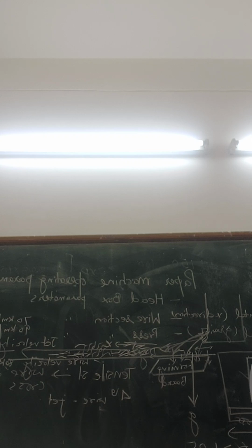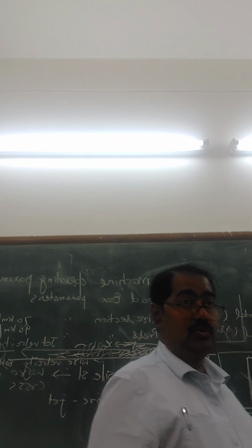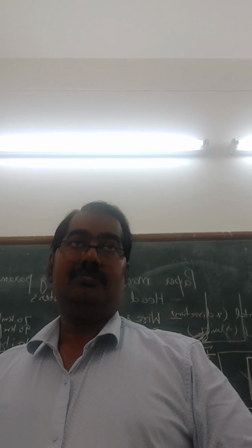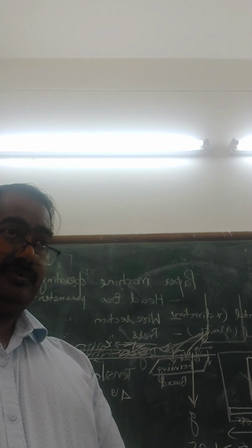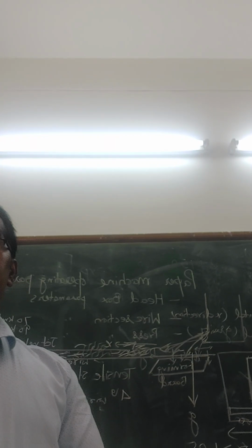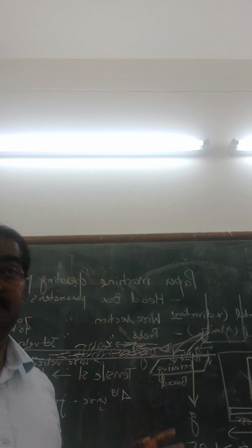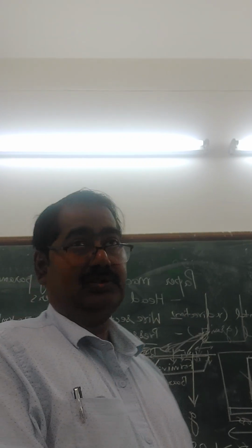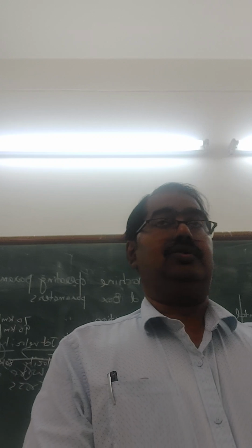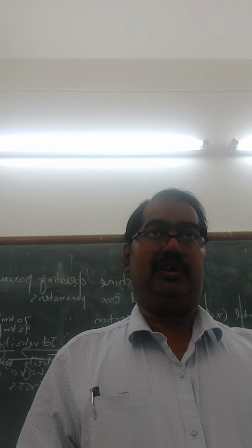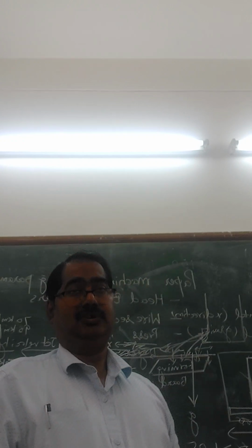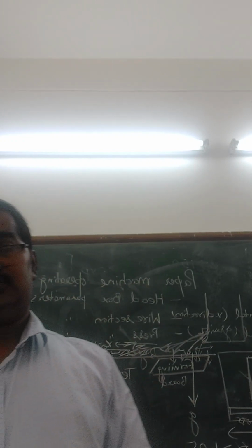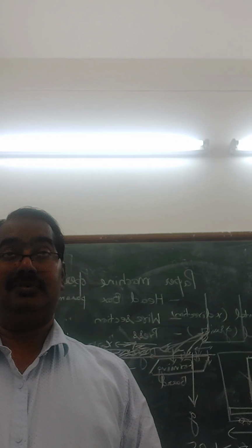Again, the formation will be good when we have the jet to wire ratio equal to 1, because the fibers will be aligned in all the directions. So it will make more uniform paper. If you see the paper in the light, you will find fibers are aligned in all the directions and it is more uniform. That is called a good formation.